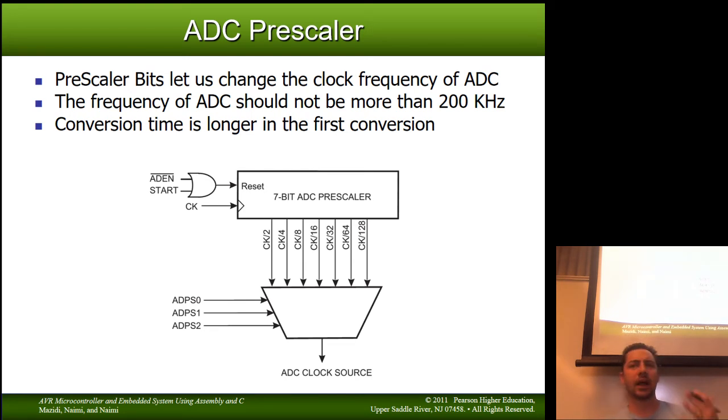The way the ADC actually does its job is it does what's called successive approximation. How many of you ever played a guess a number game and I say higher or lower? That's a successive approximation. If I tell you that I'm thinking of a number between 0 and 127, what would your first guess be if you wanted to do the minimum number of guesses? What? Half that. What's half of 127? Think about it like this, right? There's 0 to 127, so that's 128 values. What's half of 128?